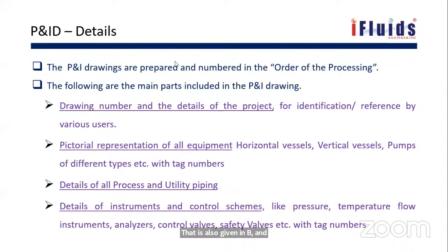So, vendor package details. A few equipments are bought as a package. Vendors themselves design and give it to us. So that demarcation is also done in P&IDs, showing where the vendor package starts. Interface details or any engineering information which requires further engineering or justification are kept as hold.